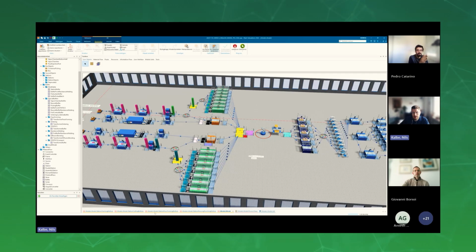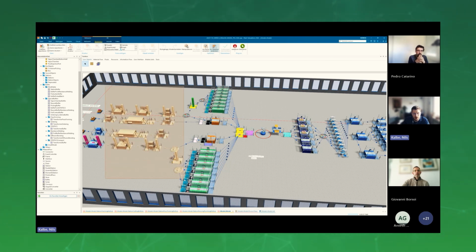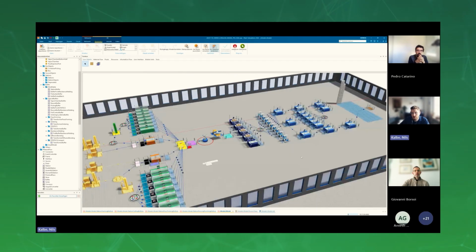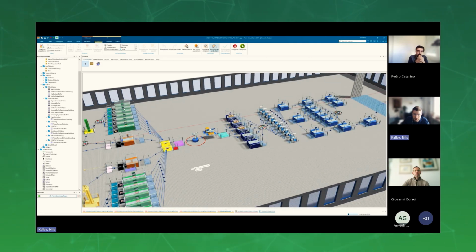In this case, the SYNTECS process, for example, is a bottleneck. I can speed up the simulation. As you can see, the buffers before the SYNTECS process are running full, and our parts are produced here in the back. And in this area, after the SYNTECS process, you have no increasing buffers. The diffusion bonding machine, for example, is not at high utilization, and not all machines have a high utilization.